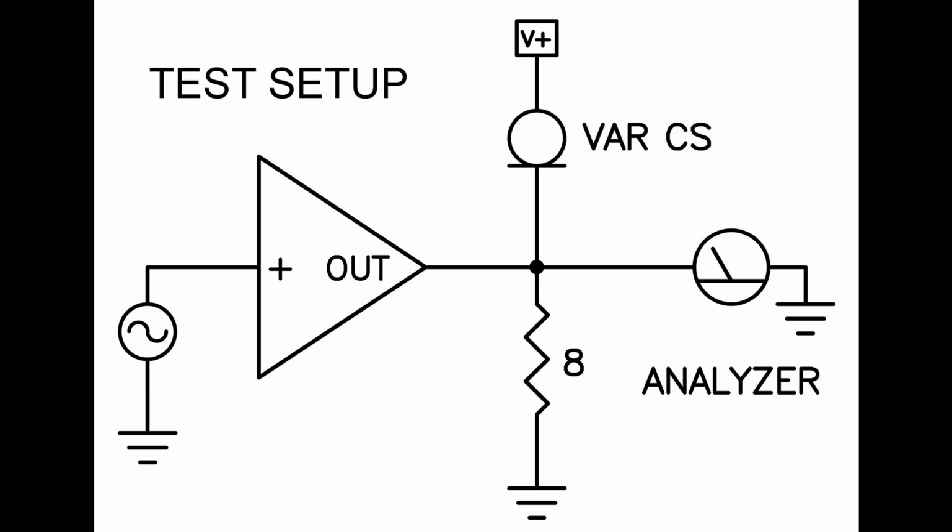Looking for a good example, I happened upon an old chip power amplifier given to me by Siegfried Linkwitz. I had measured it before, and it was an example of the school of low bias current and high feedback. I measured the distortion at 1 volt output into 8 ohms at 10 kilohertz over a range of 0 milliamps of external bias up to 500 milliamps, and I will show you the progression in 50 milliamp steps in the following little slideshow.